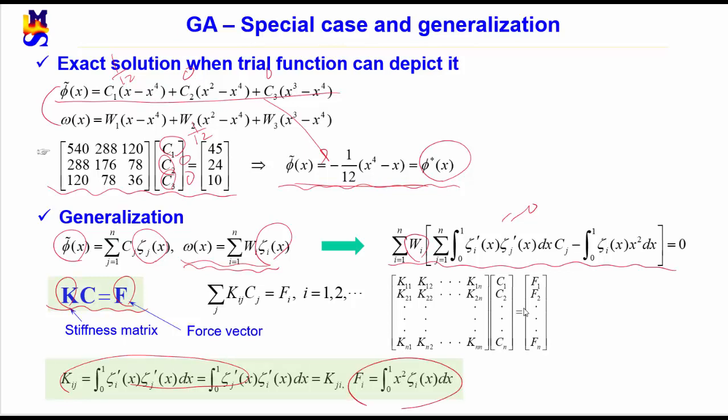We use these terminologies, stiffness matrix and force vector, regardless of the kind of engineering problems. Of course, the matrix is well-natured, that is, symmetric. It is also non-singular if the basis functions are linearly independent.